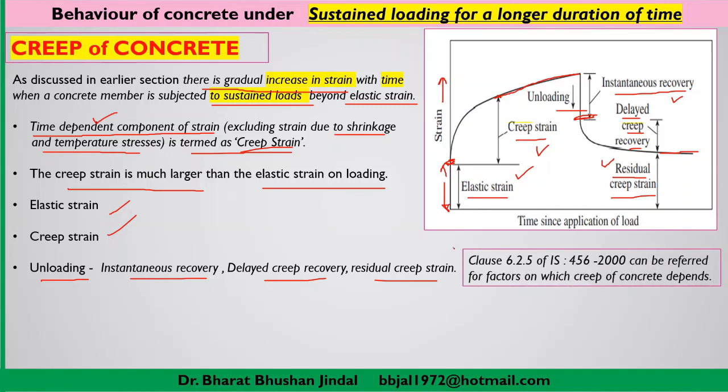Now you can refer to clause number 6.2.5 of IS 456 2000 to get the information on what factors the creep of concrete depends on. I am not going into more detail of the creep strain because it is expected that you have gone through it in detail in your earlier subject, that is concrete technology.